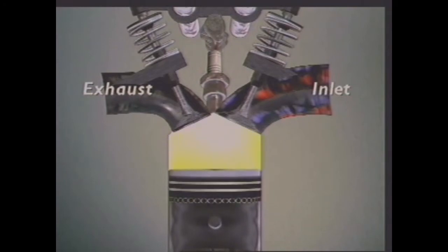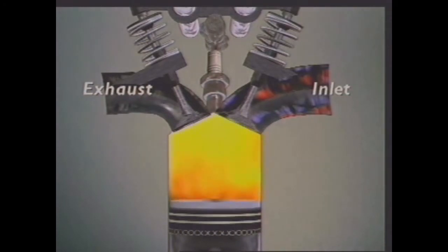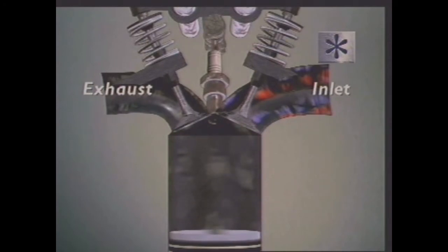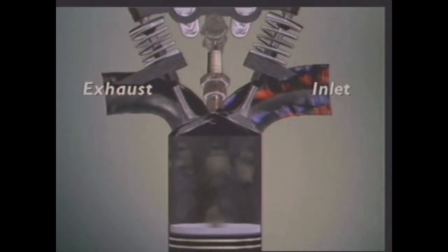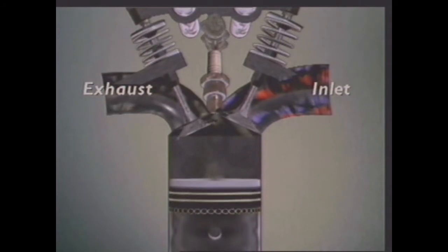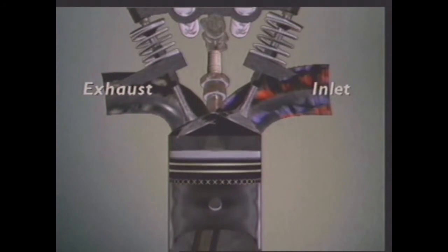Burning, expanding gas generates the force to push down the piston. This is the power stroke that drives the engine. The piston now moves from bottom dead centre to top dead centre. The exhaust valve opens and the piston pushes out the leftover gases.